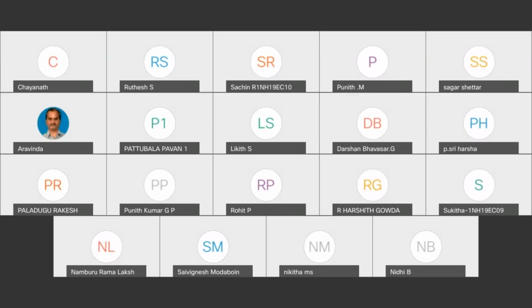We will not decide the physical size of the circuit here, because we are now dependent on FPGA, right? So when we write a code, it will be implemented with the library elements that are available in FPGA. That's all. We will not worry about the physical size, because inside FPGA there are fixed library elements such as multiplexers and LUTs. So the synthesis tool will synthesize according to the components available in the library. It will create a netlist. Based on that, output will be provided to us.